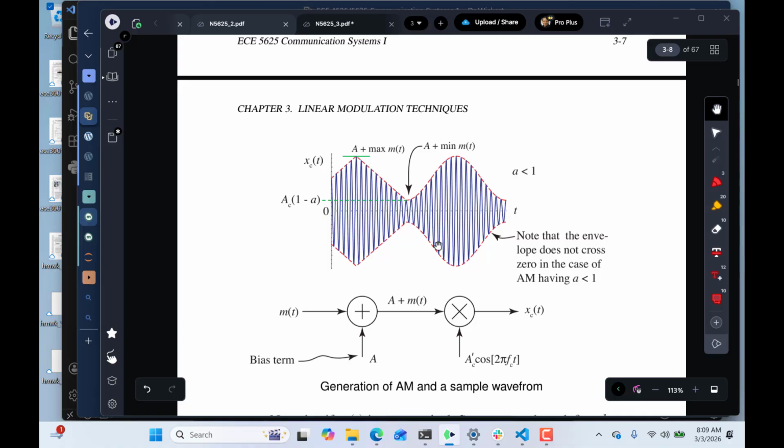In this waveform picture we looked at last week, the idea of the modulation index is that when A is equal to 1, the envelope of the modulated carrier will just be touching together, and that says it's at 100%. If it goes greater than 1.0, it will be crisscrossing through the zero axis, and that will be overmodulation, and then we can't be demodulated successfully unless we do coherent demodulation, like we did with double sideband. With AM, the idea is to make it simple and not have a complicated receiver.